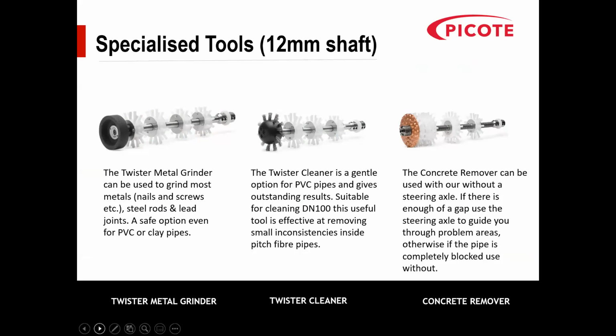We've got twister cleaners for plastic pipes. These are great for taking out inconsistencies inside pitch fibre pipes before you put a cured in place pipe through them. And for 100 and 150, we've also got concrete removers for the 100 and 150 pipes.